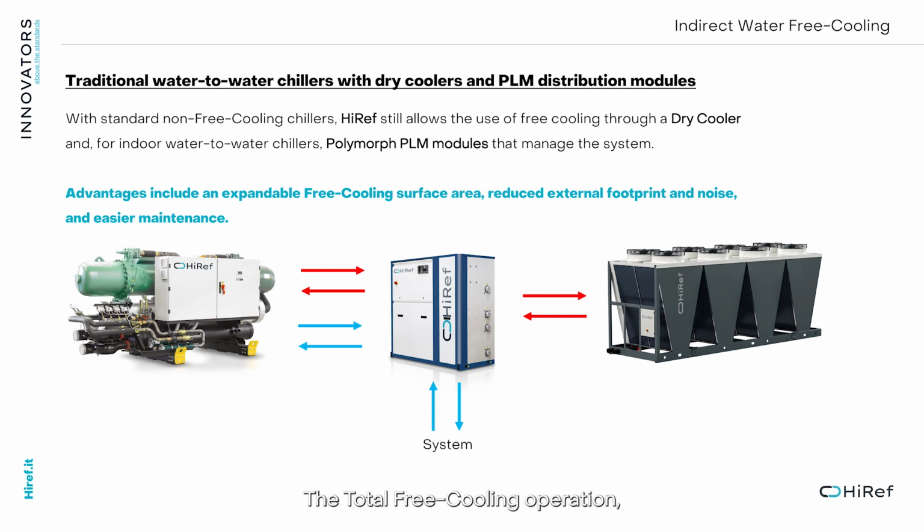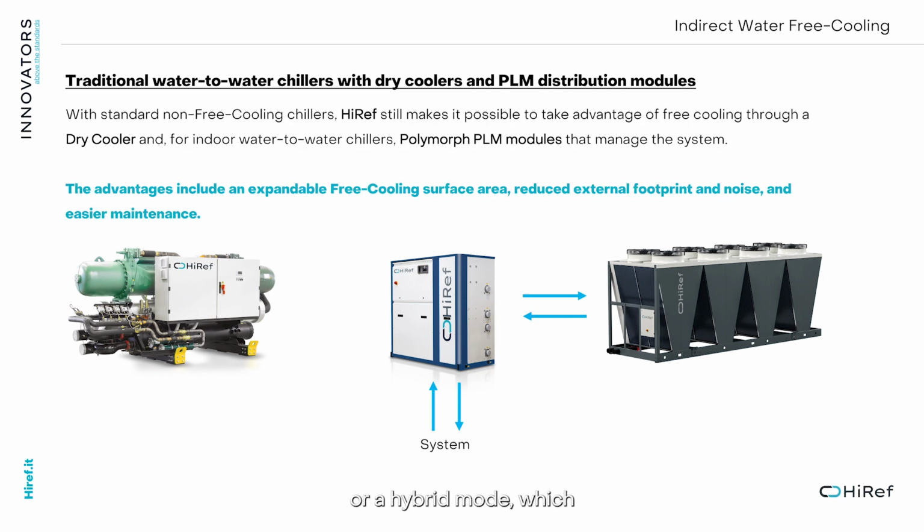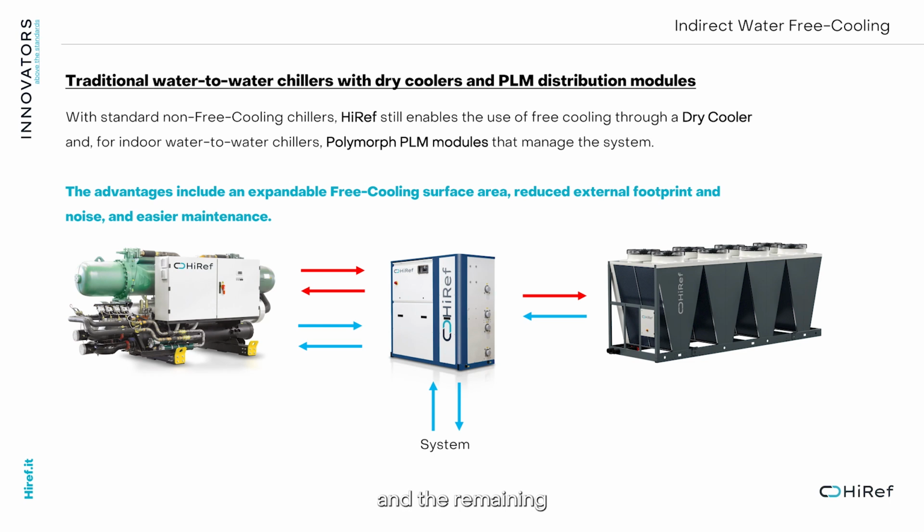The total free cooling operation, where the heat of the data center is dissipated through the external dry cooler, or a hybrid mode which pre-cools the water supplying the perimeter units of the data center with the dry cooler, and the remaining portion is supplemented with the mechanical cooling of the chiller.